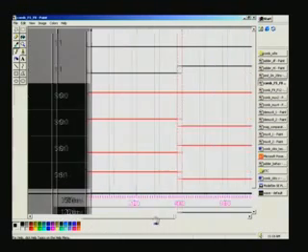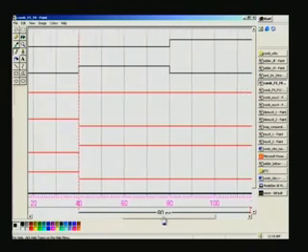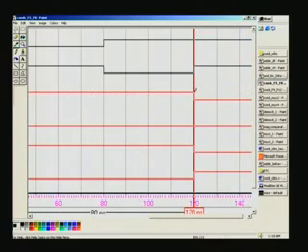And see, in this case the first output is this NAND. So this is 0, and 0 into anything is 0. NAND means not AND, so that means not 0, so 1. There should be an inversion. So this is 1 here. And here also 0 1, so again 0, not 0 is 1. So here 1 0, so 1 will continue here right up to that point. Then it becomes 0 because both are 1. So 1 into 1 is 1, and then not 1 is 0. So you have verified NAND here,